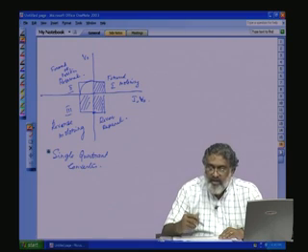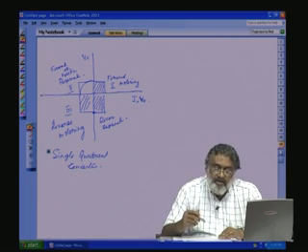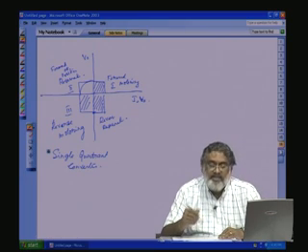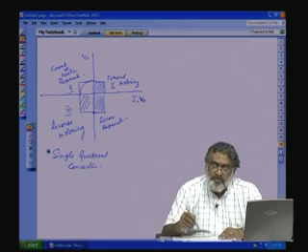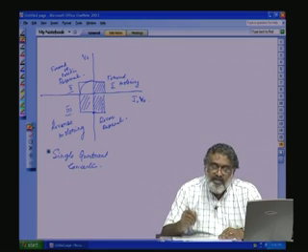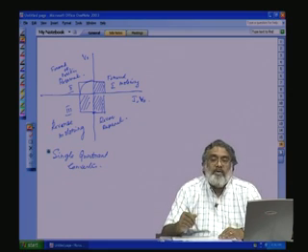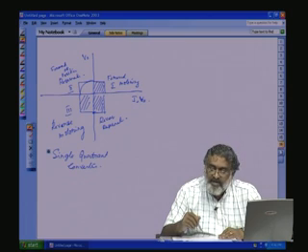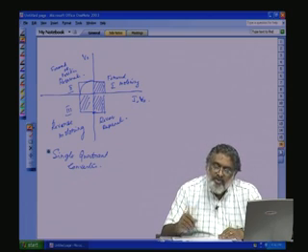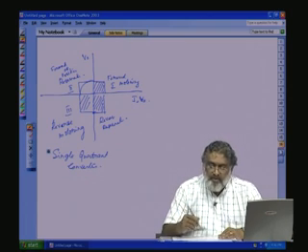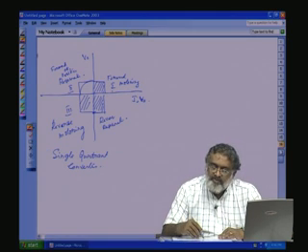When the system has high load inertia, why? To slow down the system, we have to take back the energy from the machine. So power has to be momentarily negative. So it is not possible here; it is only a single quadrant.